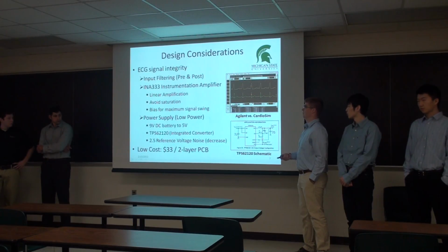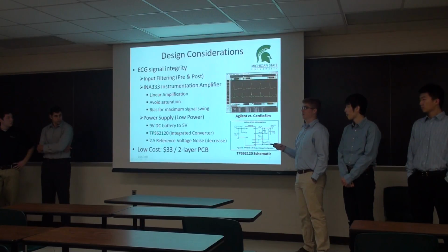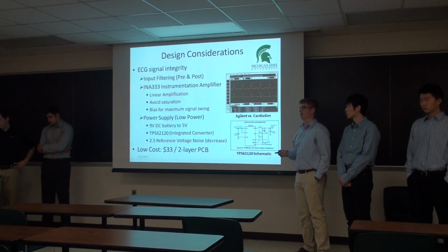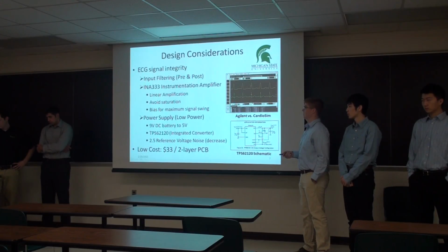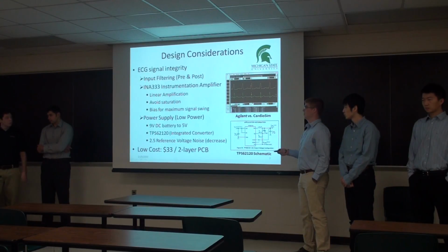Our main instrumentation amplifier for our analog front end is the INA333, which is an integrated circuit of a simple instrumentation amplifier. It has some pretty good features: low noise and high common mode rejection ratio.